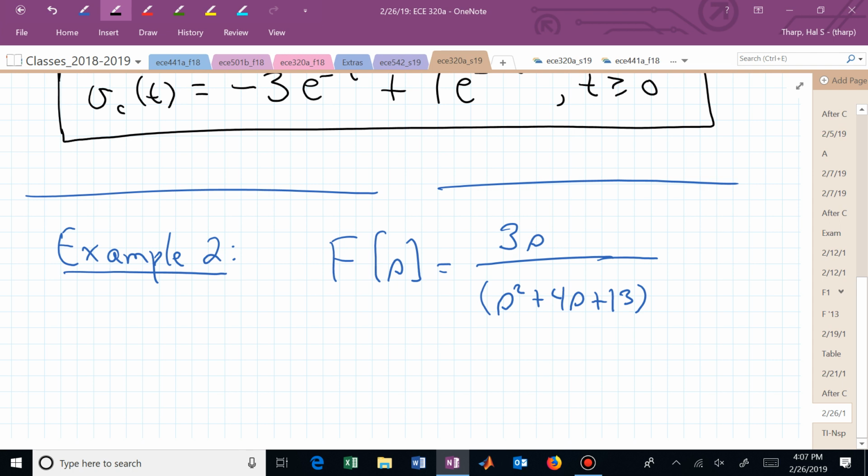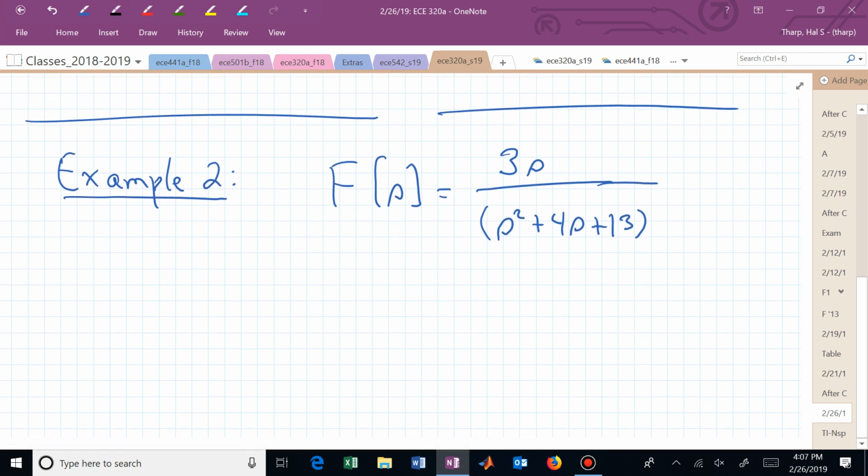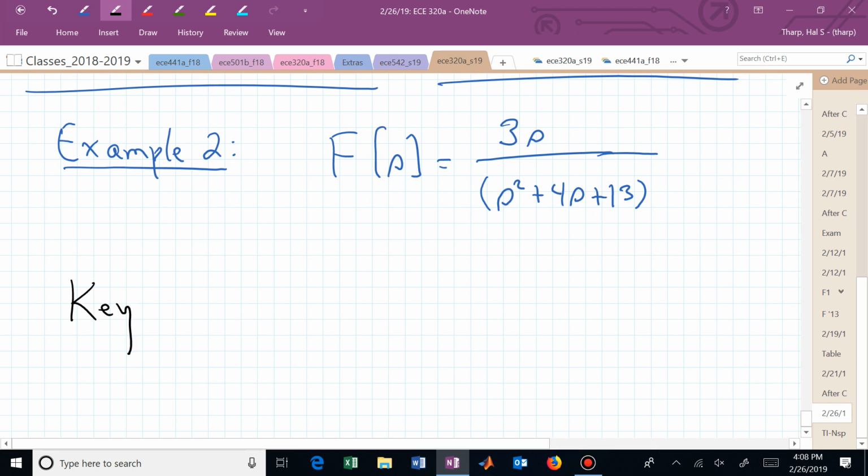And now what do we do, or if you're now trying to inverse Laplace transform, sort of what's your focus? What will you be doing when you're confronted or given some transform expression? What's sort of your first thought? Look at the denominator. See what it produces, right? What values of s cause that denominator to vanish? And those are going to be giving rise to our natural modes, or the modes of that inverse Laplace transform. We want to then key in on the denominator